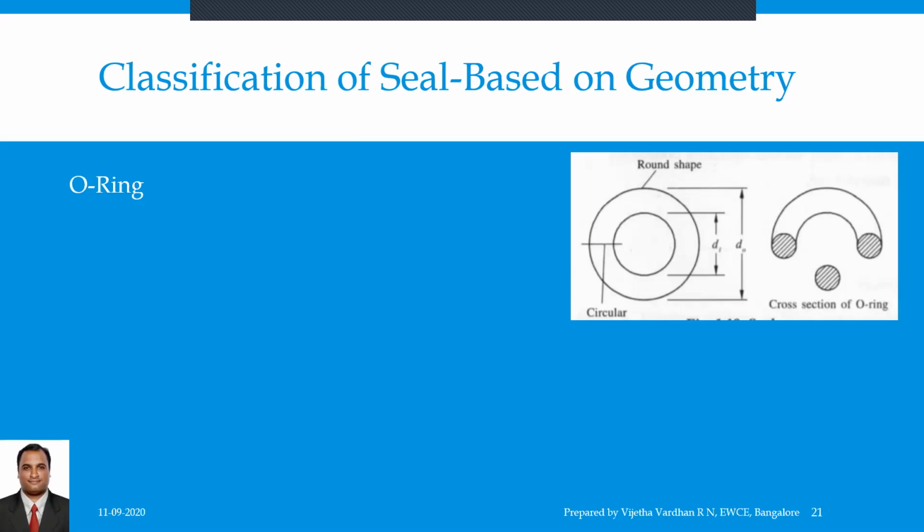Probably the O-ring is the most commonly used static seal. It comprises a molded synthetic ring with a round shape when unloaded. O-rings can be specified in terms of inside diameter for fitting on shafts or outside diameter for fitting into the bores, as shown in the figure.